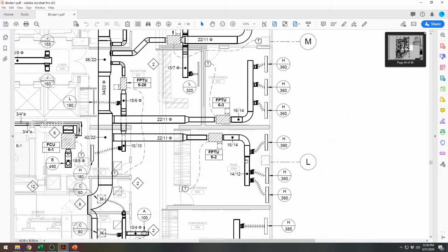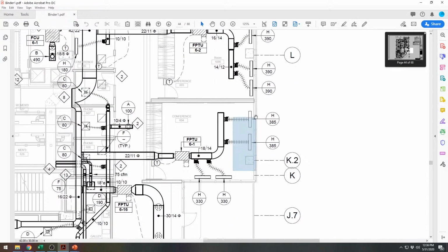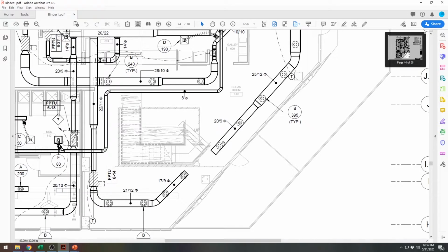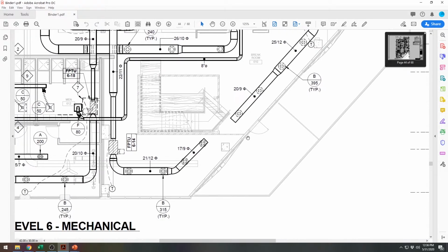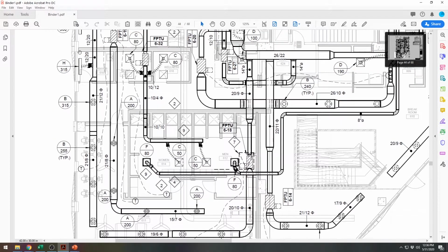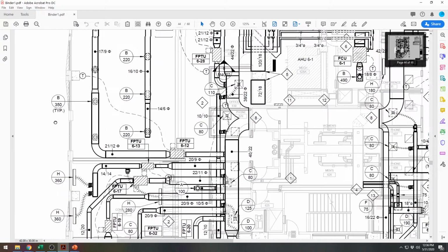And then notice there's a lot of attention paid to the exterior of the building. So really most of the heat load, your heat gain nowadays, referring to summer anyway, comes from sun coming in to the windows and basically heating up these areas. There's a lot of attention paid to the direction that the building is and how much heat is coming through the windows. So basically there's a zone here.